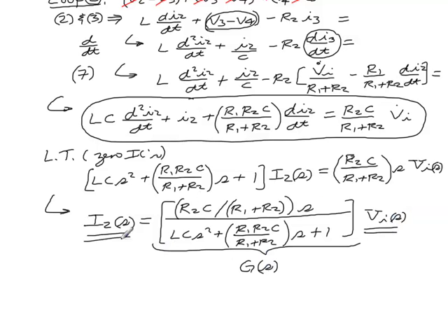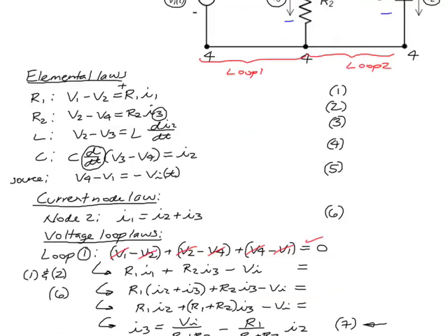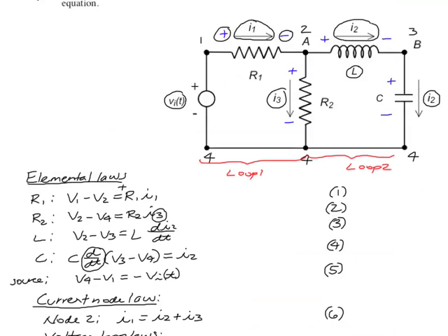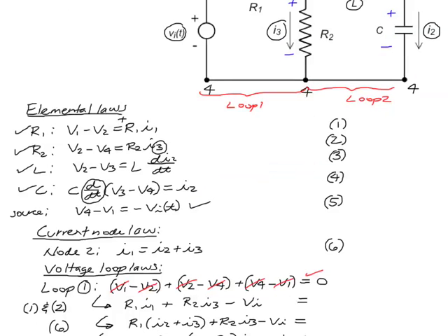So the process we went through was a tedious one, I think. We had to be on our toes right from the beginning, particularly in sign convention. So it's very important that you label your currents. I usually label those first, then go back and put my plus minuses on the voltages, because that gives us the correct signs on elemental equations for R1, R2, L, and C, as well as for our input.